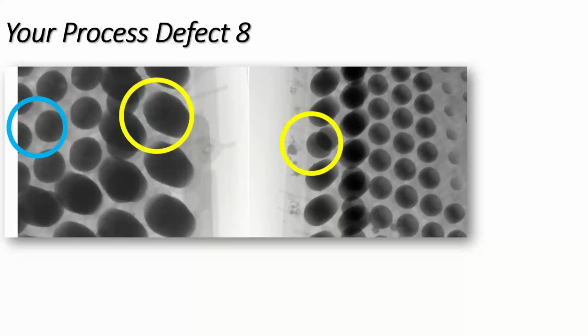The balls haven't soldered together, which may be process related, the flux dipping process, dipping into solder paste, the dip paste that we use, or a warpage problem, which has contributed to that particular problem. So you've got to investigate 2 or 3 areas, but I would suggest it's probably warpage related. So if you know the history of the component, how much warpage you get during reflow, you'll be able to overcome that. But if you've got a problem, and let's say, for argument's sake, you were using a dip flux for this process, I would investigate using a dip paste.